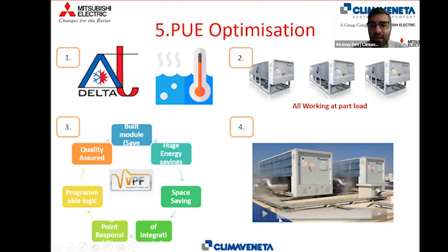It's a big saving. And finally, we spoke about adiabatic kits. As you can see, these are chiller. Adiabatic kits are nothing but having a misting system on the condenser coils of chillers. You can have this in any of your chiller equipment. Of course, please do not choose this in ambients which have very high RH. It may not be very useful to you.